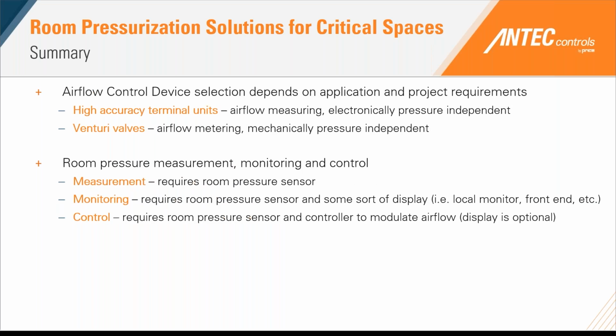Additionally, we talked about the different types of airflow control devices you can select depending on your application and project requirements. Again, with your high accuracy terminal units, you are taking live airflow readings. It's going to be electronically pressure independent with the usage of an actuator controller. And then we also have a Venturi valve, which is an airflow metering valve. It's mechanically pressure independent. It's able to control airflow without taking those live airflow readings directly in the airstream.